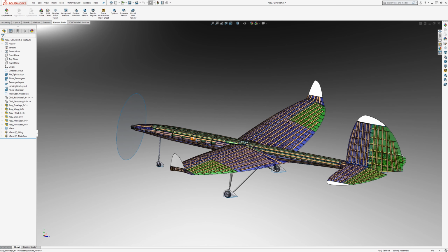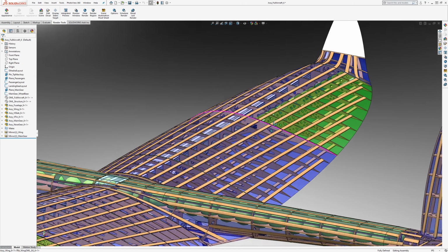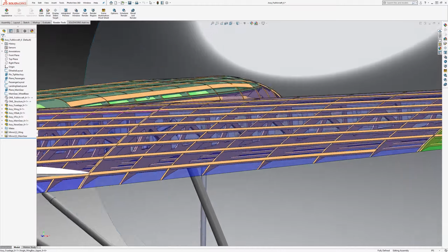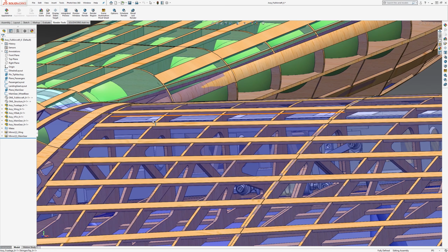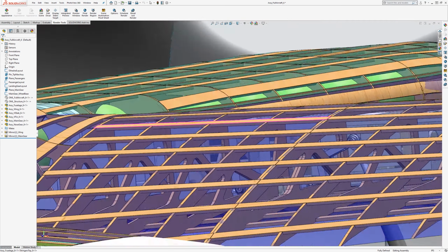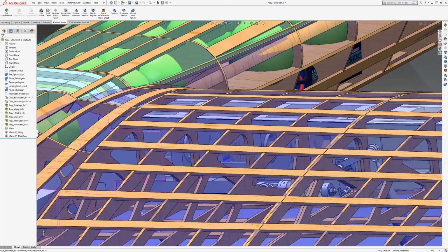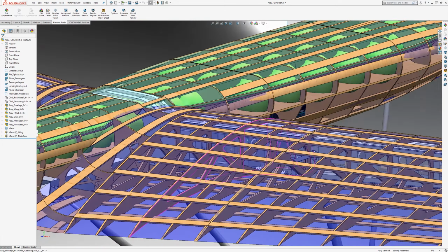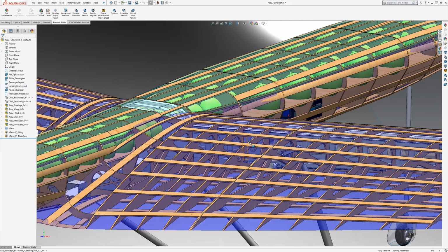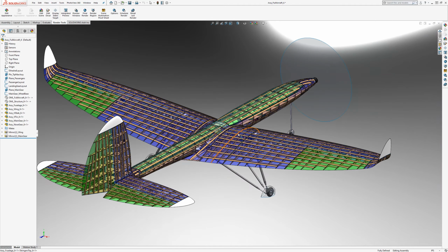What you might have at this stage is an initial design of the internal metal structure, as well as a layout of where the passengers and the cargo and the systems will be positioned. We'd have an initial estimate of the performance and maneuvers, and the wing and stabilizer and propulsion performance, everything we need to move that mass around. Now, if our internal structure layout is dependent on the external surface, like it is here with these wings, because the wing box is as close as it can be to the outer surface of the aircraft, so this inner structure here depends on the outer surface. So if you have structure like that, then you'd have closer to finalized outer surfacing of the aircraft.